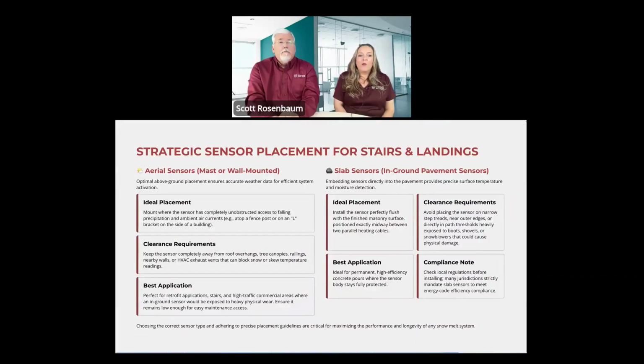Absolutely. Before I forget, sorry, I hate doing this, but I said 3/4 inch rigid metal conduit. That's the National Electric Code. The code book will say "or other approved means," which in a lot of communities now is becoming PVC.